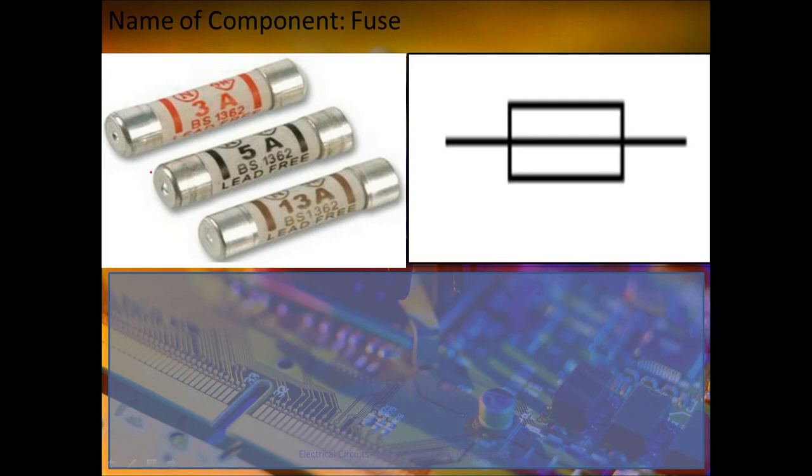So you can see on the ends of the caps of these three fuses is a little mark. That is the welding point for the fuse wire, which would run through the center of the fuse to the other cap. So that is essentially joining one cap to the other in order to complete the circuit. So these are always fitted on the live wire.